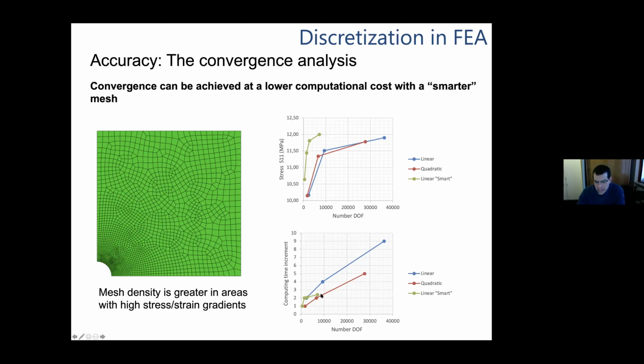So in this case, when you do these adaptive meshes, or specific or local mesh refinements, as the one that we did here, the idea of performing these operations is to maintain the number of degrees of freedom as contained as possible, so that we keep the total computational cost somehow bounded, but we increase the quality of our solution to acceptable ranges.